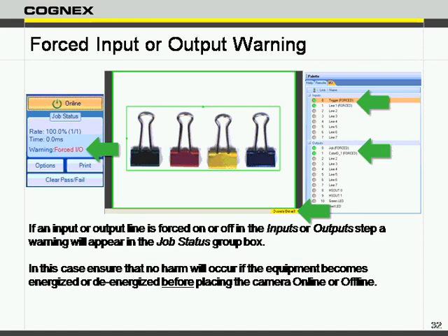And like I say, when we have our forced input and output functions, we can also see it in that lower left-hand pane down here. It'll show as forced I/O. And we also have in our I/O tab the indicators with the LEDs. They will turn either gray when they're not used and green when they're high. Those are the only two states that you will see them in. We don't have red or green. We have just the gray state, not used, or green, indicating they have gone high.